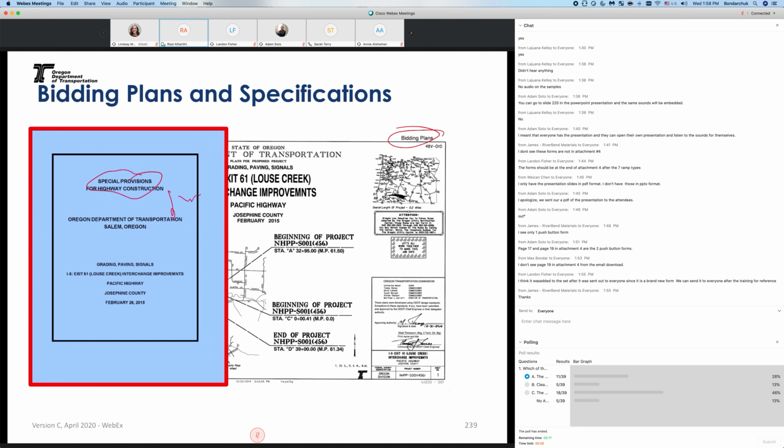So when you see these two, those are during the bidding process. The bidding process is usually 3 to 4 weeks. And during this bidding process, contractors usually submit requests with questions and so forth. And the agency and the engineer of record respond to those and they may add addenda. And this addendum may alter these plans and specs.